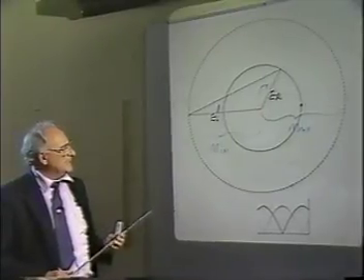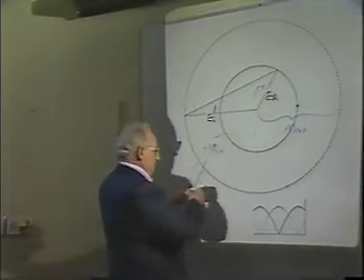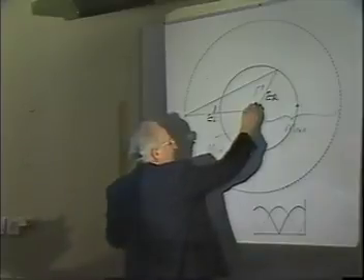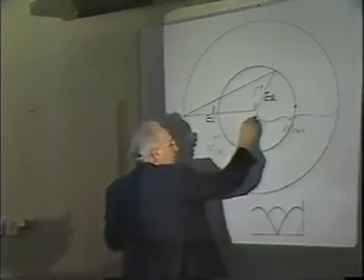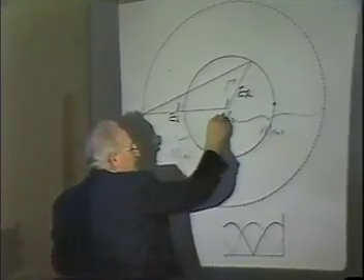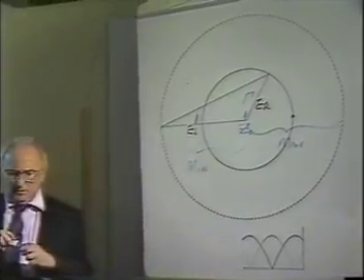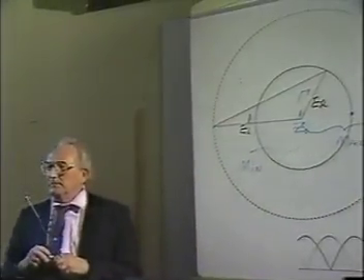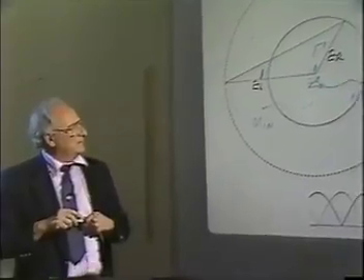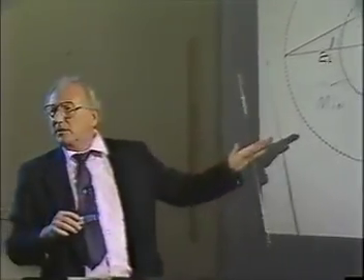Okay? What's the center of the chart here? Well, if it's 1, that means you've normalized it. But we know that that center of the chart represents the characteristic impedance of the transmission line. So that's enough for that particular diagram.